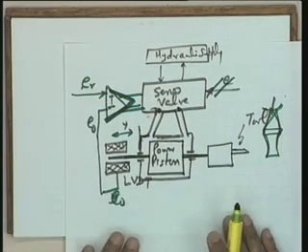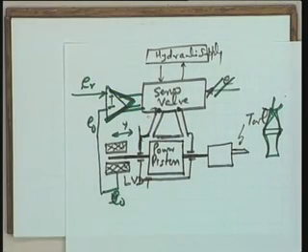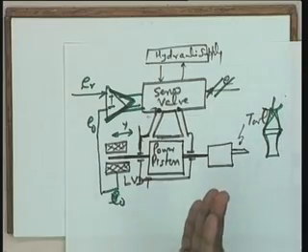Now this signal has been generated, and it becomes the input to the servo valve, and hence this completes your electro-hydraulic control system, in which, instead of the lever, which in the earlier case was acting as an error detector, an operational amplifier is now acting as the error detector. The advantage is not only limited to a lever having been replaced by an operational amplifier. The advantage is much more than that.